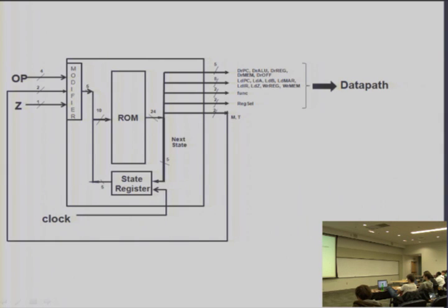And so now if you look at the control unit, we've got the ROM, which contains all of the microcode that you've written, and you have the state register that is saying what is the next state you want to go to. And these are all the static signals coming from a particular ROM location. From that particular ROM location, you're driving the data path using the drive signals, using the load signals, and the function that has to be supplied to the ALU, and the register selection.